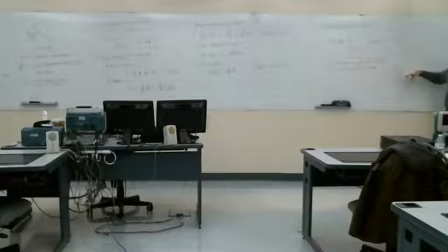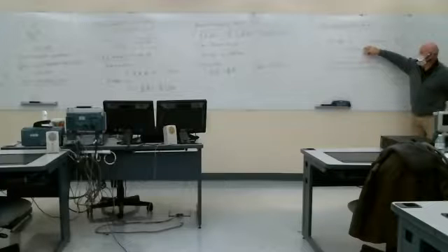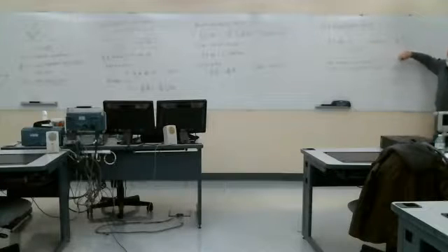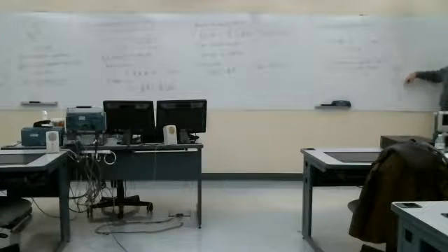In the time-varying case, though, I do have current here that's changing, and so I get a right-hand side here. I get current going into and out of the capacitor, but really no current through the capacitor, right? What I'm really doing is charging up one plate and discharging the other on one cycle of the sinusoid, and on the other cycle of the sinusoid, just reversing the polarity, then charging up the other plate.